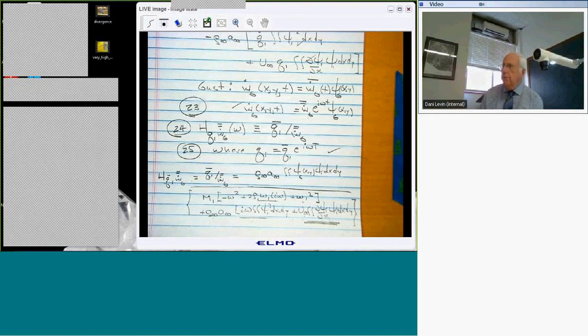And some of you are turbomachinery enthusiasts. Typically, turbomachinery people historically have only looked at that kind of flutter. We could have a whole discussion on why that's so, but usually in turbomachinery, most of the flutter that occurs is a loss of aerodynamic damping, negative aerodynamic damping. In fixed wings, that's not true. Well, it is and it isn't.